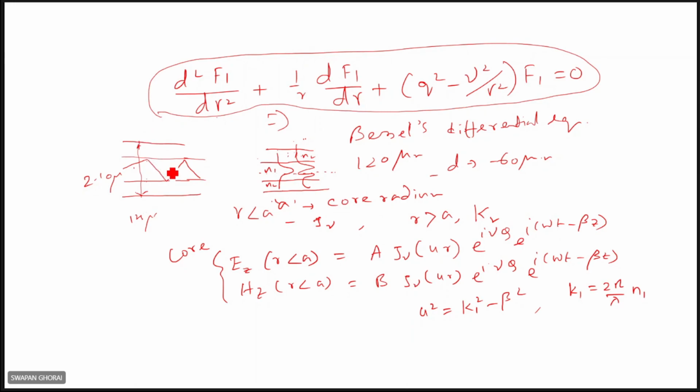because modes are propagating like this. You see it here. This is the fundamental mode, and this is a higher order mode. Higher order means several peaks can be there. If a single mode is present, then it is similar to a Gaussian distribution. That is, as I told you, the HE11 mode, right? That is the fundamental mode.